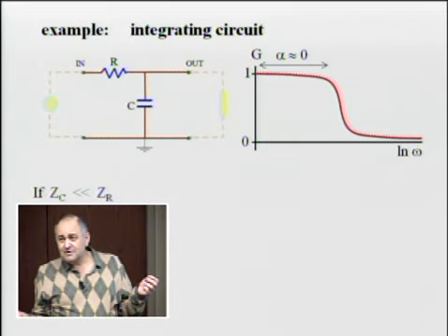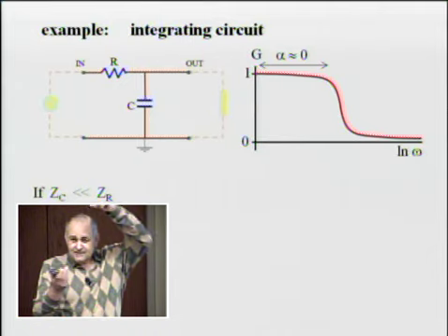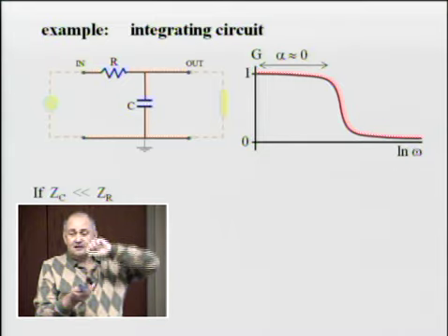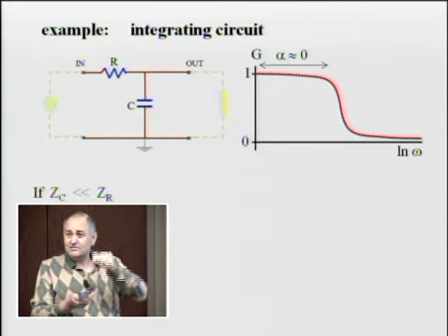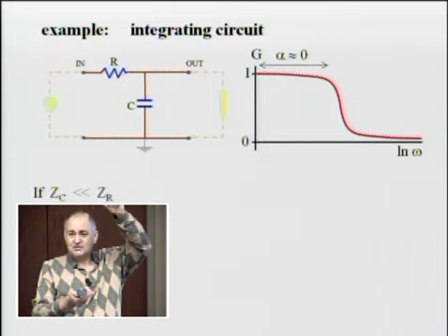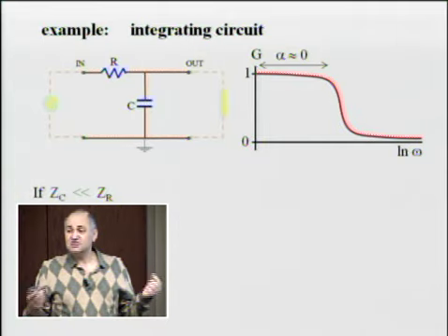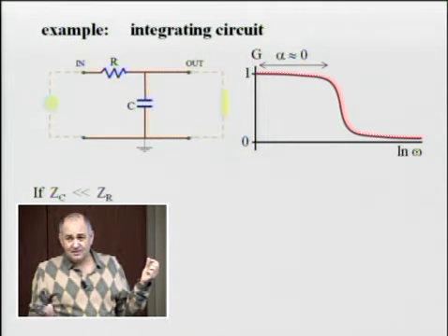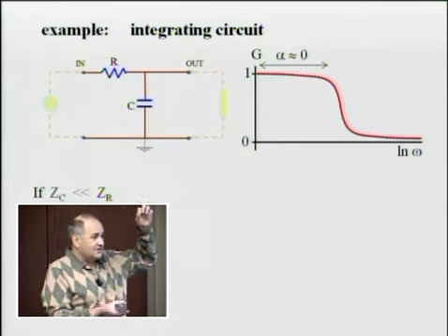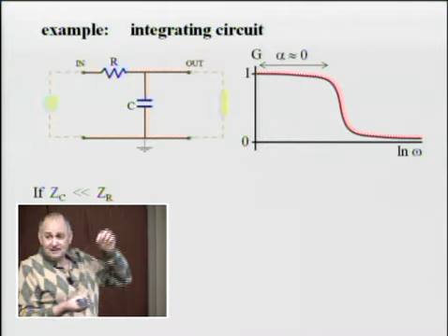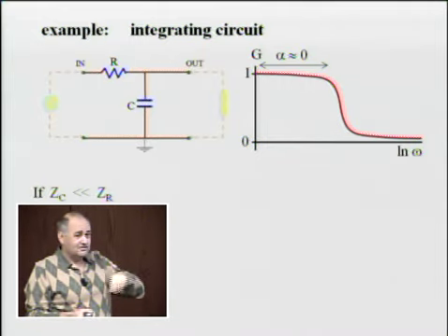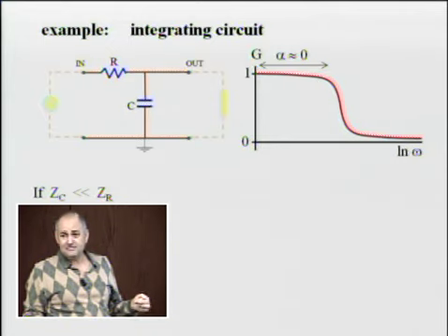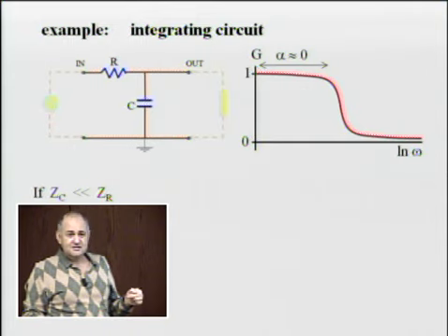You remember how when we arranged two resistors, the voltage across one resistor was a fraction of the voltage across the two resistors, with the ratio determined by resistances. Well, here we have the same thing. The voltage across one element is a certain fraction of the voltage across the two elements together, determined by the ratio of their impedances.